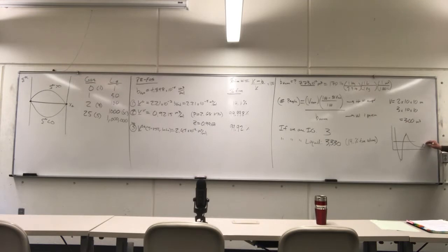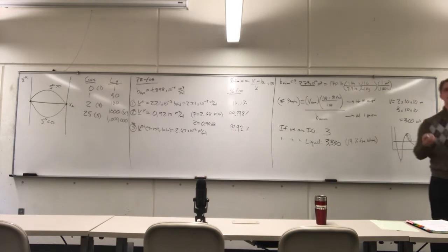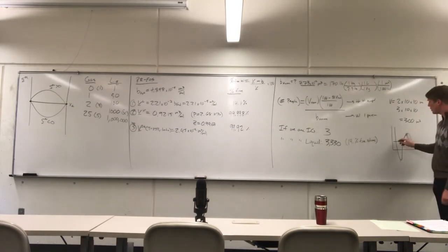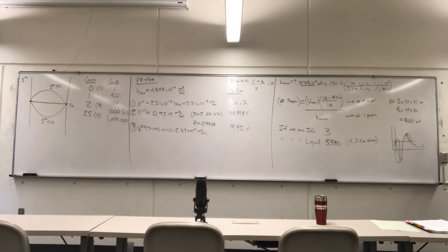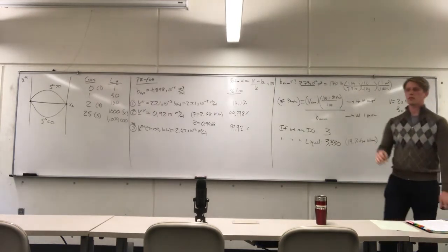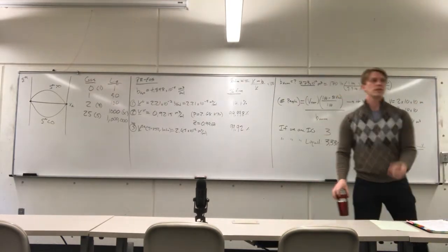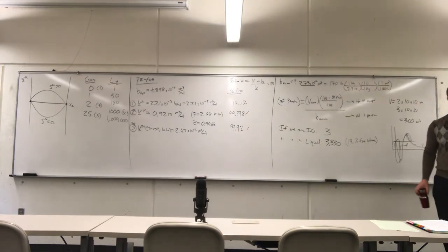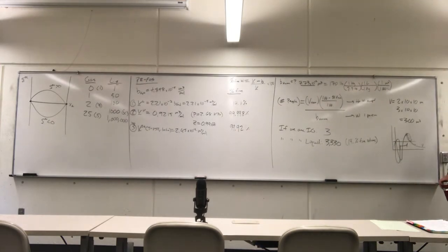So if I'm starting off here as a vapor and I'm getting pressurized, I can interact in this area over here a little bit, right? I can be a little bit subcooled and still be a stable fluid. Likewise, if I'm a liquid, I can be superheated a little bit and still be a stable fluid. But there is a region in between here that, according to the second law of thermodynamics, says you cannot be in this region because it doesn't behave as the universe would be if it were a stable system.